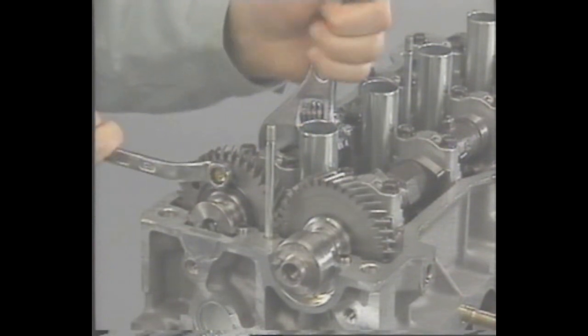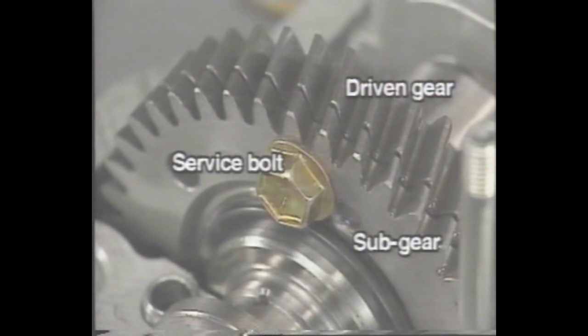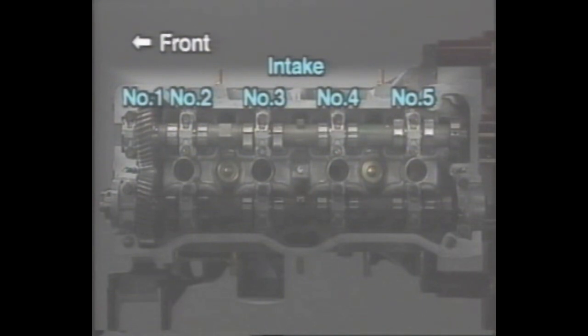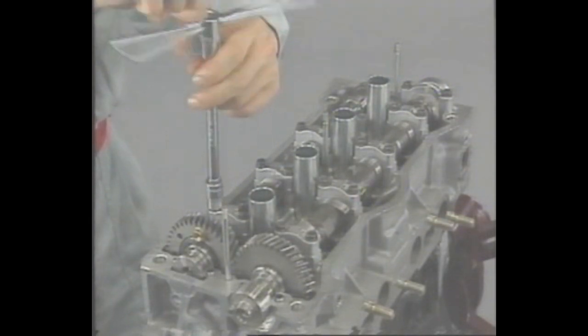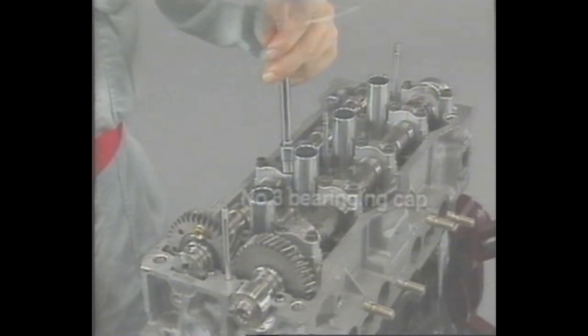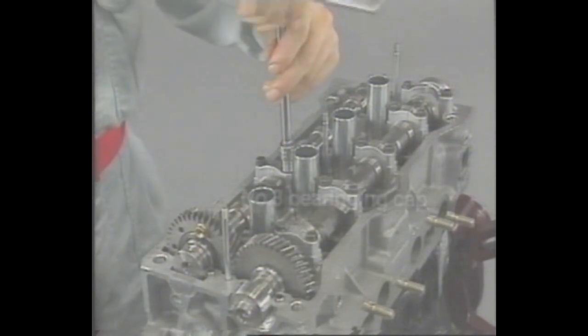Holding the intake camshaft with a wrench, secure the subgear to the driven gear with a service bolt. Remove the intake camshaft bearing caps in this order: number 5, number 2, number 4, and number 3. To remove the bearing caps, uniformly loosen the bearing cap bolts little by little. For the number 3 bearing cap particularly, loosen the bolts very carefully, little by little, in several passes, so that excessive force is not applied to the thrust portion.